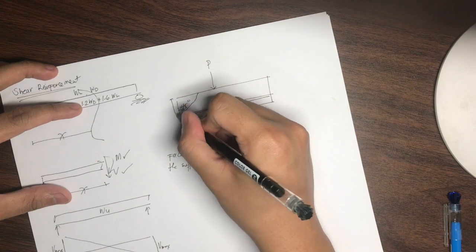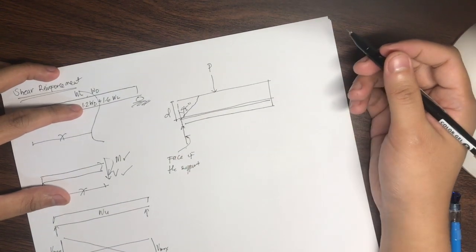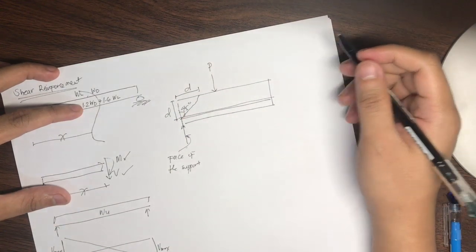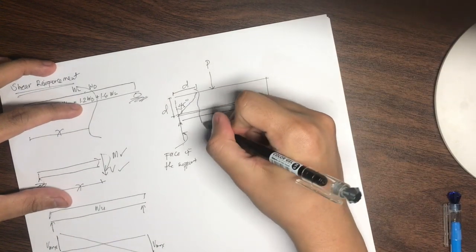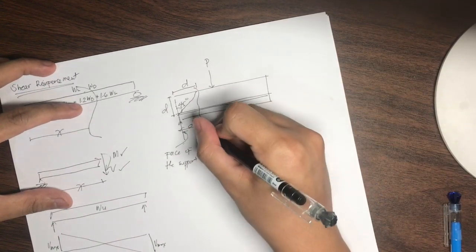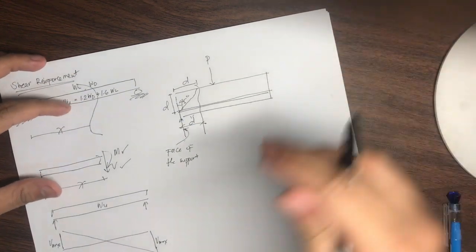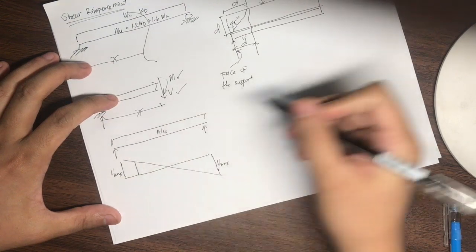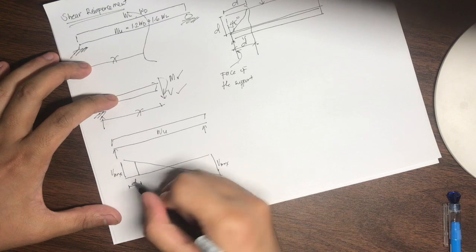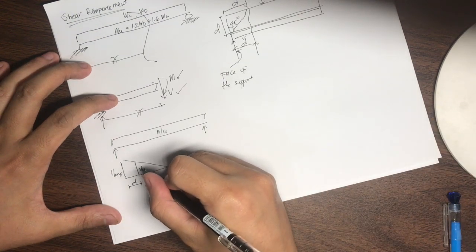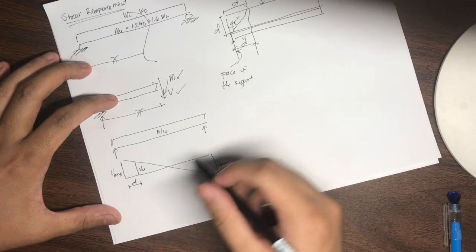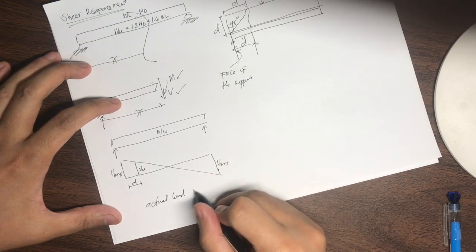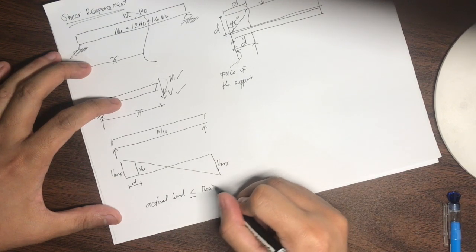Now, if this is what we call the effective depth or the D distance, obviously, this distance is also the effective depth D. So in that case, yung failure pala natin is actually occurring D distance from the face of the support. That's why in this diagram, we will be considering your ultimate shear at a D distance from the face of the support, and that will become your Vu. And we all know that the actual load must always be less than or equal to the resistance load.